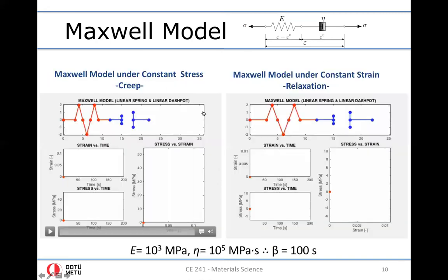In the upcoming slides, starting from this slide, we will see a bunch of movies where the behavior of the Maxwell model will be demonstrated for different kinds of loadings, for different values of the material parameters, especially the relaxation time. For the simulation demonstration purposes, I have selected the Young's modulus equal to 1 gigapascal, eta equal to 100 gigapascal seconds, and therefore the corresponding relaxation time is 100 seconds. In this slide, we have the creep response and the relaxation response of the Maxwell model together.